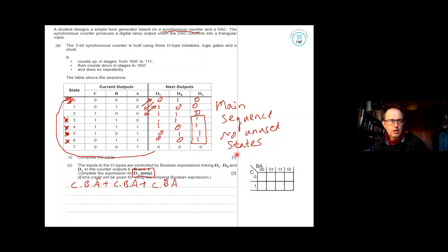Practice that. So each one of these, I'm looking to see what the Boolean is for each one of them, in terms of A, B, and C, just where the ones are. Now, what you could do is to try and simplify that by using Boolean, but that's something that's really hard when you've got loads of terms. Now, if you can transfer that into a Karnaugh map, it becomes really easy to simplify it. So I'm going to just transfer the ones in.